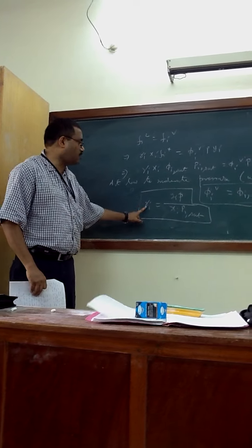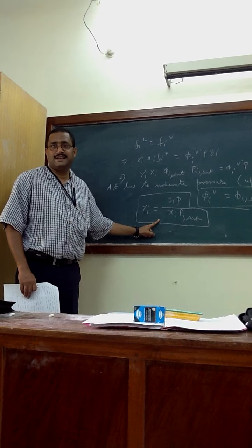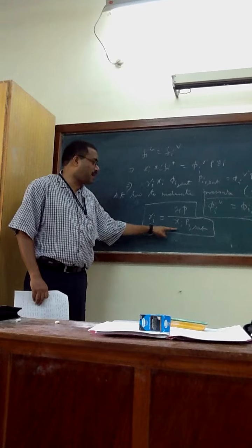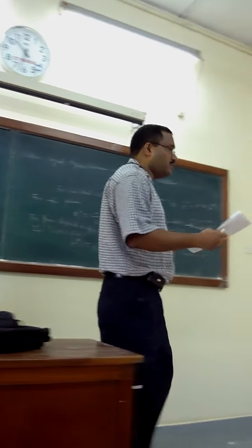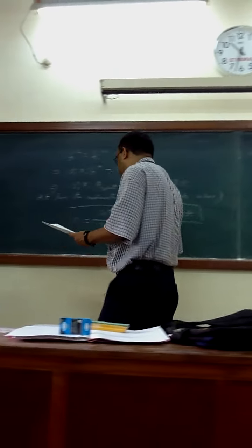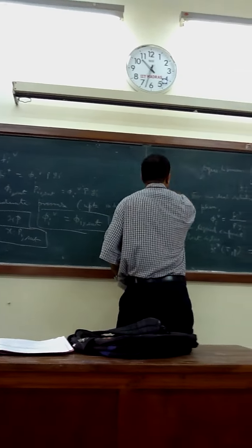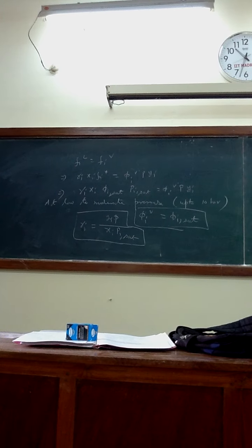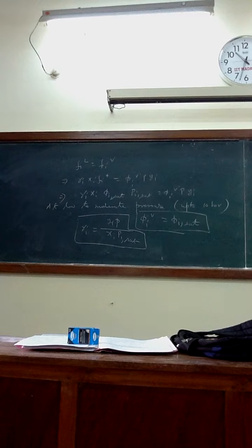For Raoult's law, gamma equals 1. We had yi P equals xi Pi sat. If Raoult's law is not valid, you get gamma i is nothing but yi P by xi Pi sat. So equation 4 reduces to Raoult's law for the ideal case. Now, if you want to calculate the total pressure, the bubble pressure or dew pressure calculation, the pressure calculation is very easy. Temperature is a problem, as you have seen. You have to use an iteration technique.